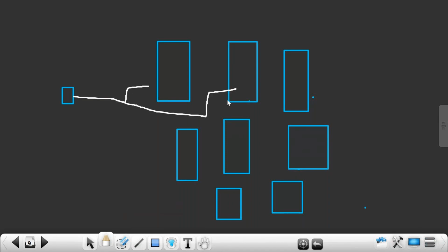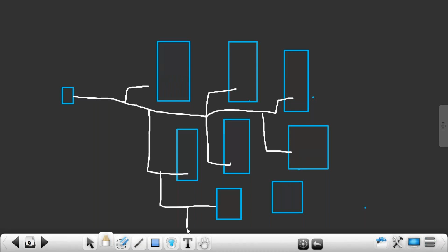Generally the flip-flop count will be like 2000 or 3000 in the design. So this clock port is connecting to all the 2000 flip-flops. What is the load on this clock port? Every flip-flop has its own small pin capacitance, and you also have net capacitance.